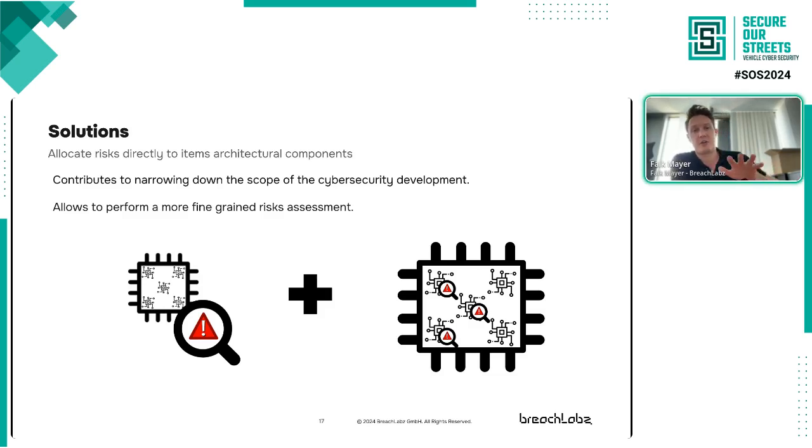The allocation of the scope for cybersecurity development is very crucial because of the ECU, for example. We see this from a penetration testing perspective all the time. Yes, you have maybe not protected your debug ports properly, as a bad example. But you would have to have physical access to that ECU in the vehicle, and that takes a significant amount of time. If the ECU supplier is not considering that and they have the ECU always in front of their table, and the pen tester does as well, we end up with very severe ratings.